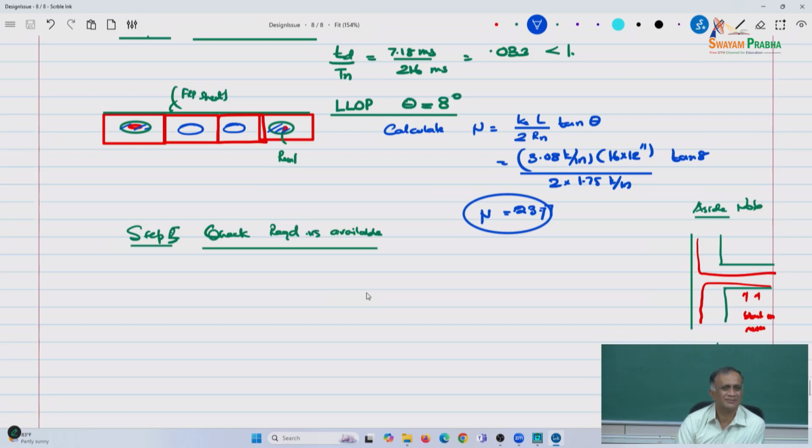What are you thinking? Mild steel plate. Well, you're changing properties. Yes, I mean, A, it's expensive. B, it's heavy. Third, how are you going to integrate mild steel plate, how are you going to connect these plates to the brick wall, right? So that's not a solution I might go with. It's prohibitive in some ways.